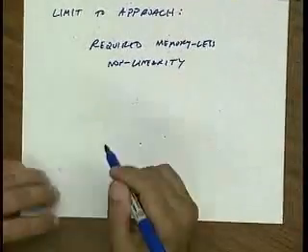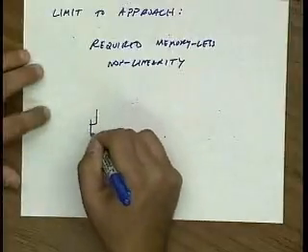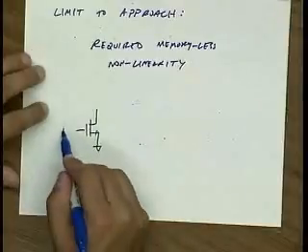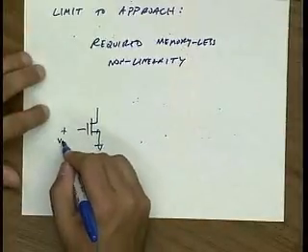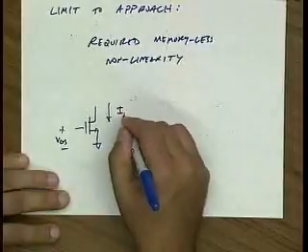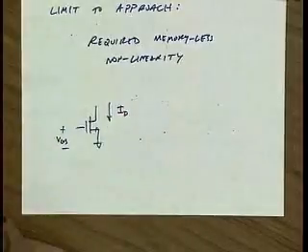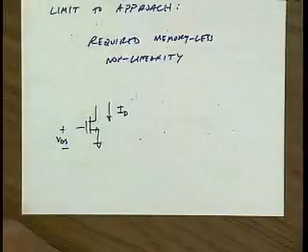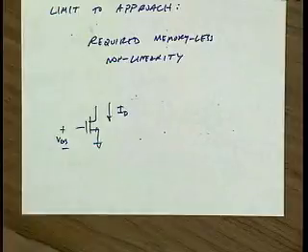Let's look at a transistor, right? Let me look at a FET and apply a large signal VGS here and see what kind of current it generates. Now, what kind of elements inside this FET would generate distortion that has memory in it? Yeah, the capacitors, right? Everything else is memoryless.